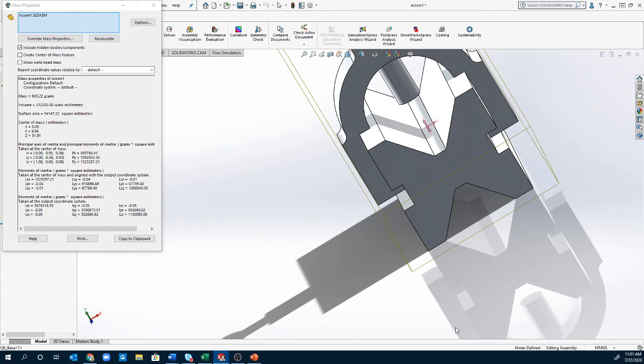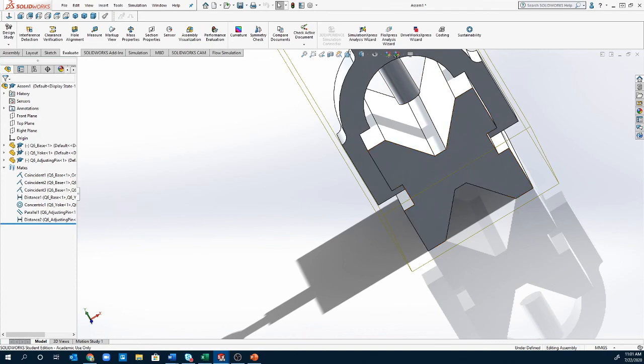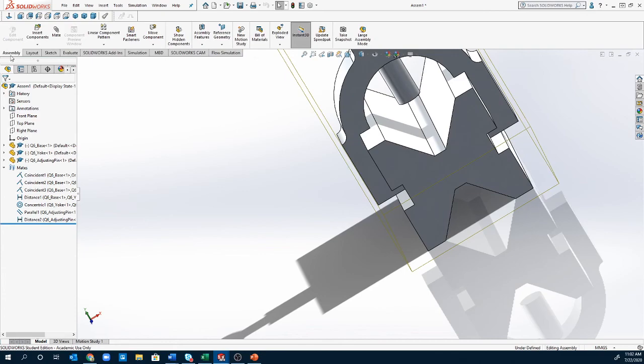But let's say, for example, that we want to find it relative to a fixed axis. Now, on things like CSWA, this is actually a fairly common question to ask. They ask you what the center of mass is, which can be found in the middle of this page where I just highlighted, and they give you where the origin should be. So one thing you could do is you can attempt to mate the origin to that location. Sometimes that works well, sometimes that doesn't. So an alternate way to do this is using a reference coordinate system, and I'm going to show you how to do that right now.